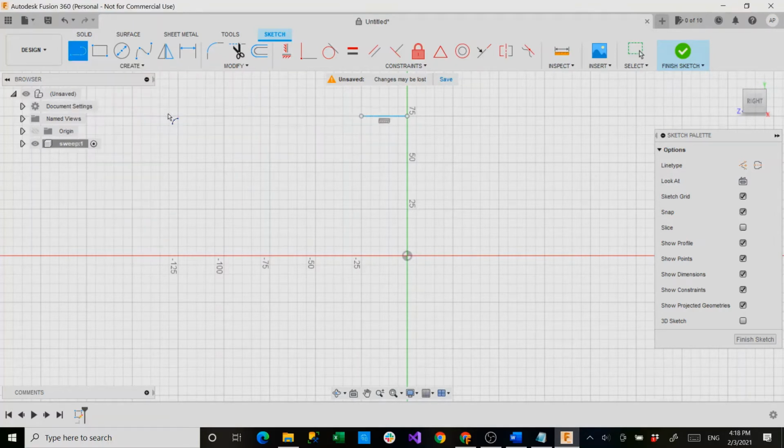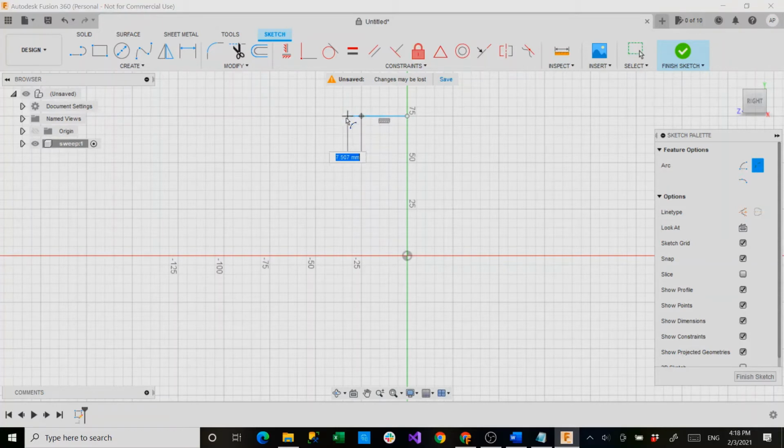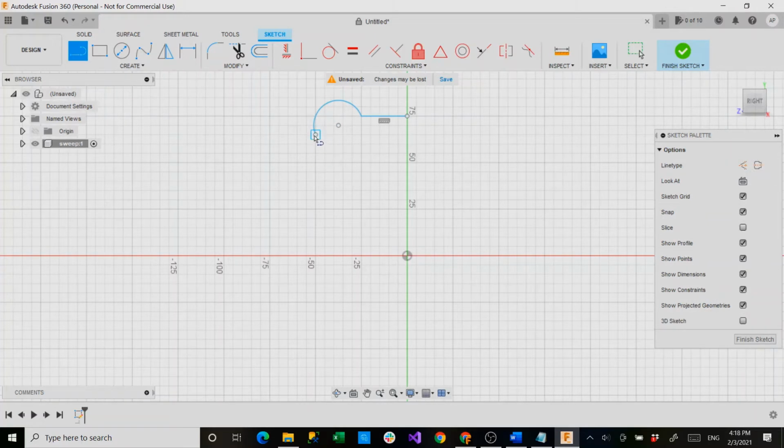And we will make a 3-point arc. Our 3-point arc will touch down about here. And you'll go out to the point vertical to that endpoint and 2 spaces up. Now you'll start another line, and you'll go straight vertically down from our second point, and about 3 blocks down from our arc. Now you'll go down about 25 millimeters, and across to the origin.